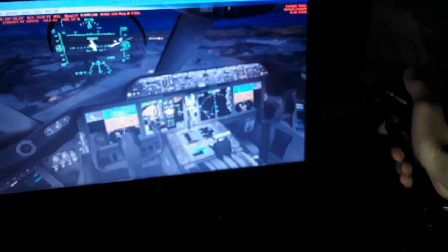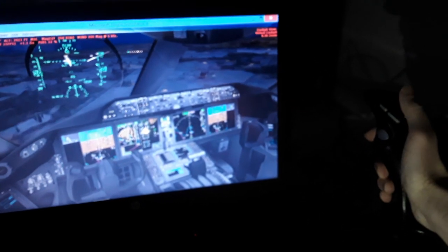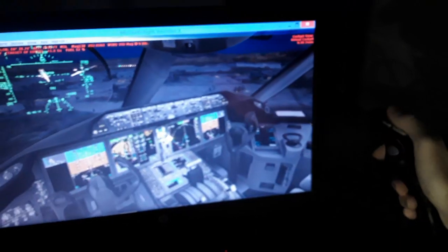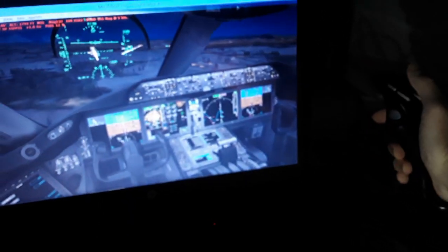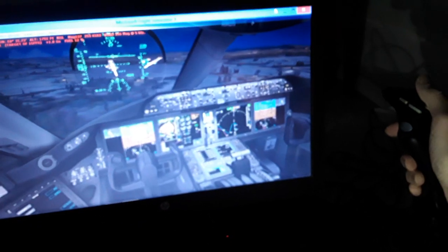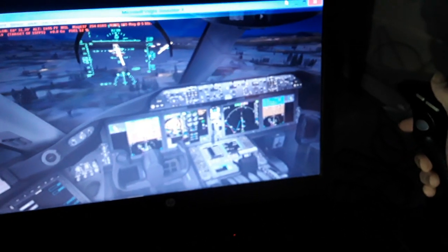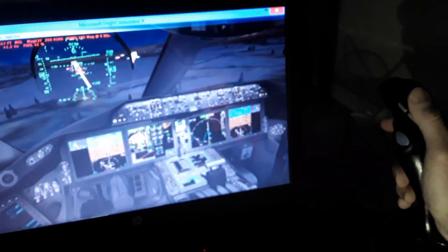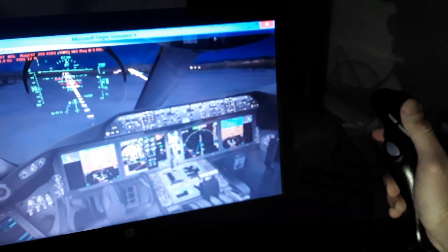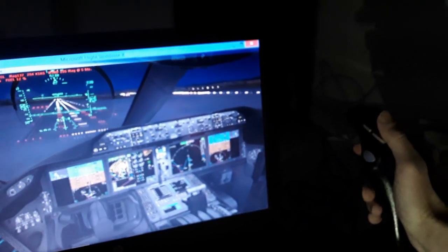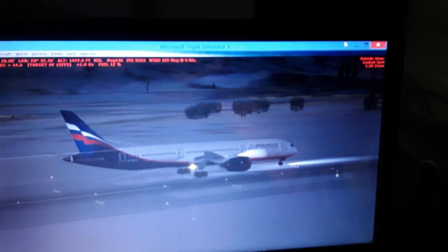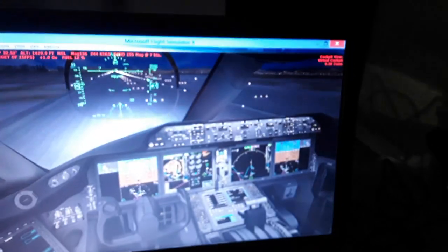Unfortunately, maybe we're not gonna make it to the landing and touchdown part. We won't have the record time. So we have 10 more seconds over here for the touchdown. So here we are aligned, flare over here. So we flare the aircraft, as you can see. Beautiful touchdown, parking brakes and thrust reverse, idle thrust over here.